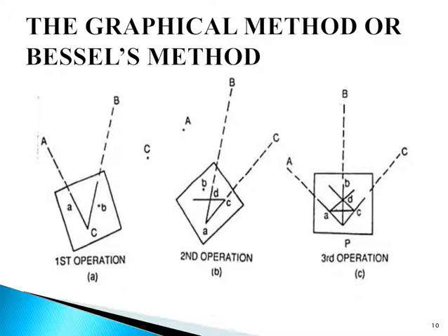The table is placed at the required station P and leveled. Then the alidade is placed along the line CA, and the point A is bisected. The table is clamped with the alidade centered on C. Point B is bisected and a ray is drawn.